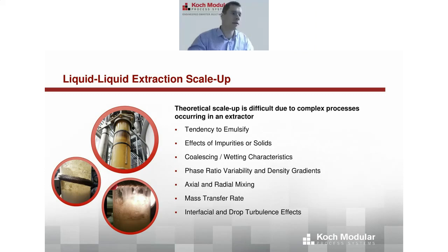Thanks, Don. And like Don said, my focus of today's presentation is going to be particularly on pilot testing and why that's so critical when you're developing a liquid-liquid extraction process. The reason you really want to pilot test before just designing an extraction column and installing and starting it up is because there's a lot of interesting, complex chemical phenomena that can take place at the liquid-liquid interface.